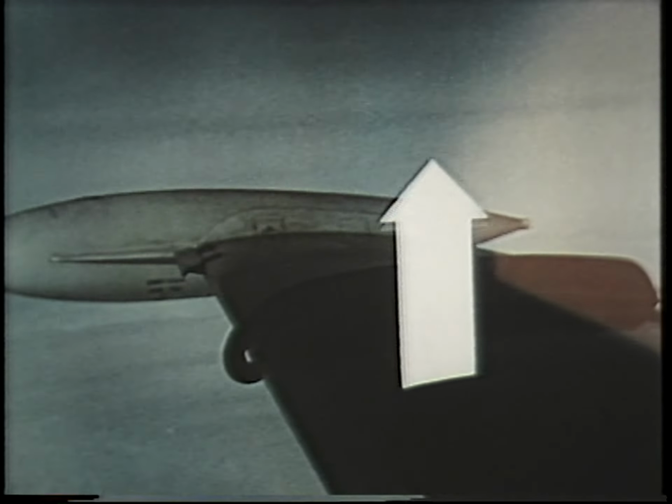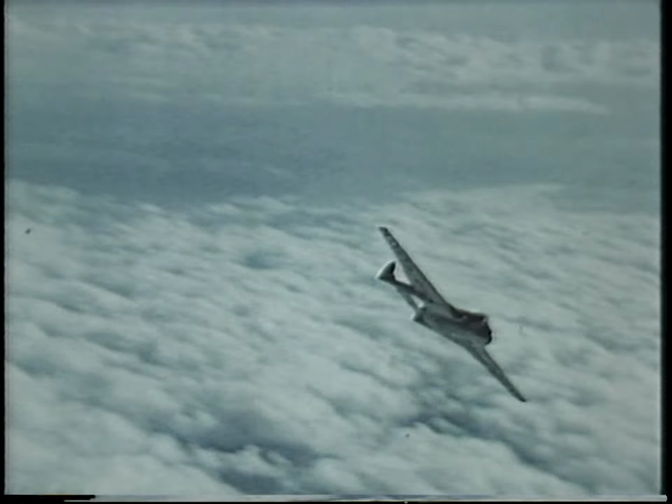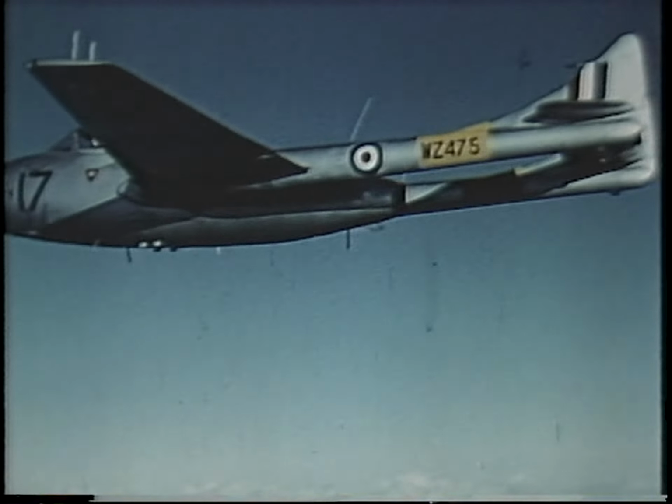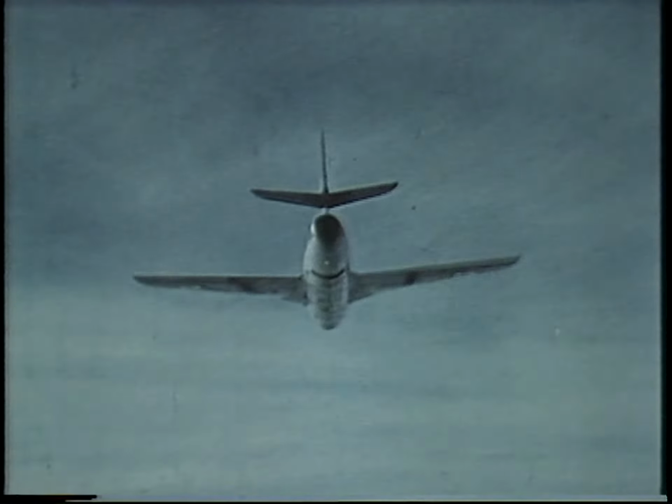Most of the other ill effects of shock waves arise because they cause the airflow to separate from the wing's surface. This produces a large wake of turbulent air behind the shock wave, which alters the pressure around the wing. This in turn may cause loss of lift, and some aircraft may lose height. In others, one wing may drop. The aircraft may pitch, or porpoise as it's called, or undergo other weaving movements such as snaking and Dutch roll.